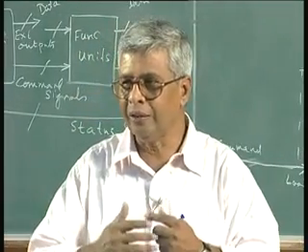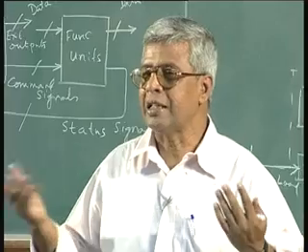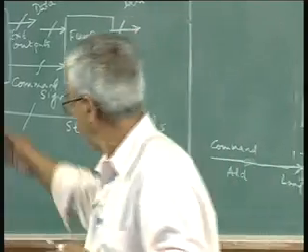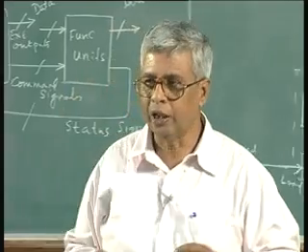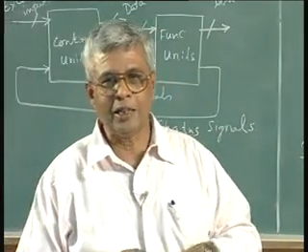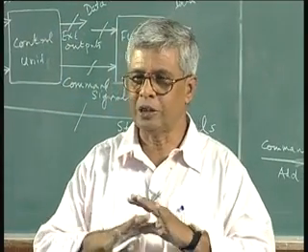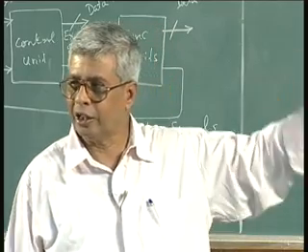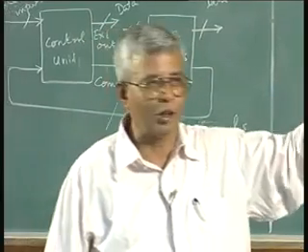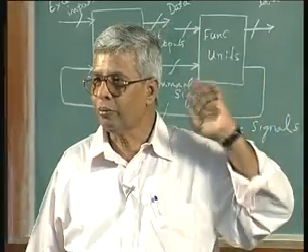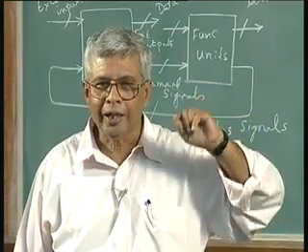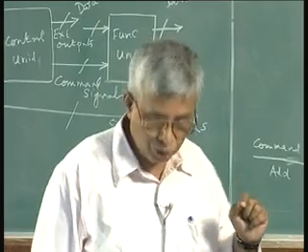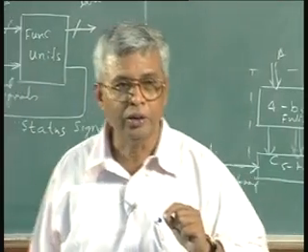Once I am done, rest is easy. I do not have to teach you how to do a functional unit, and a control unit as a state graph. Once that stage is completed, it is sealed. From then on it is a state graph, transition table, flip flops or multiplexer base, ROM base, PLA base. Again and again I am emphasizing this fact. I might have told you this 100 million times in this course.